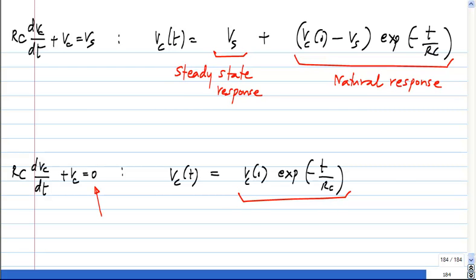The function on the right hand side is known as the forcing function. So what happens is that initially you will have some characteristic of the circuit that is coming in. For instance, in this case, the forcing function is DC, right? It's a constant with time, and eventually the solution also becomes constant with time. But before it gets there, there is some part of the solution that's really a characteristic of the circuit. Here, for instance, we don't have a forcing function at all, and we have an exponential which has minus t by RC, an exponential whose time constant is some characteristic of the circuit. It's related to the components in the circuit.